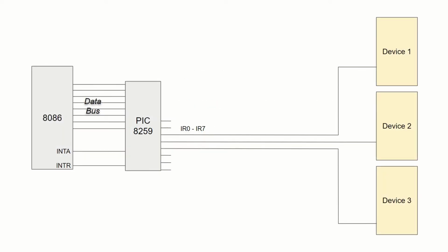As a quick reminder from the previous video, when an interrupt is raised, and now I mean the regular maskable interrupt raised by the INTR pin, the 8086 acknowledges it by setting its INTA output to 0. This is a signal to the PIC that it needs to provide the CPU with the vector number to be called. It means that we need something which can drive the data bus bits when, and only when, the INTA is active.